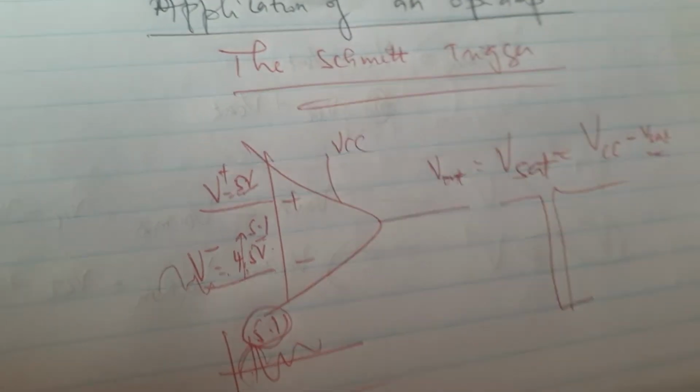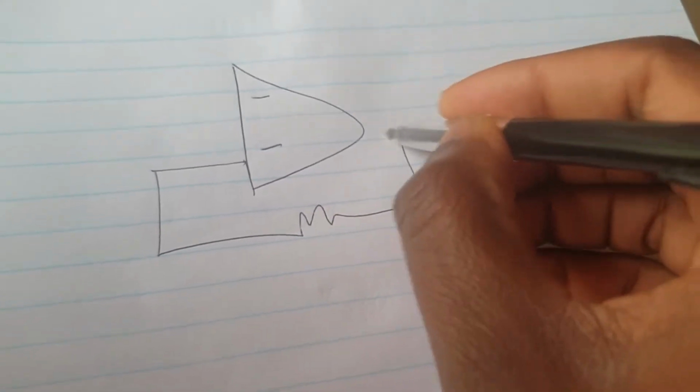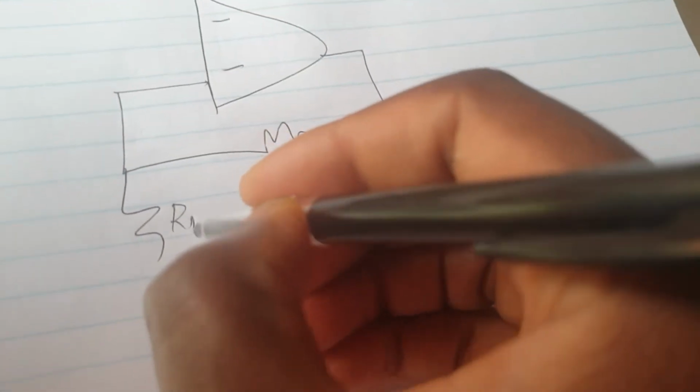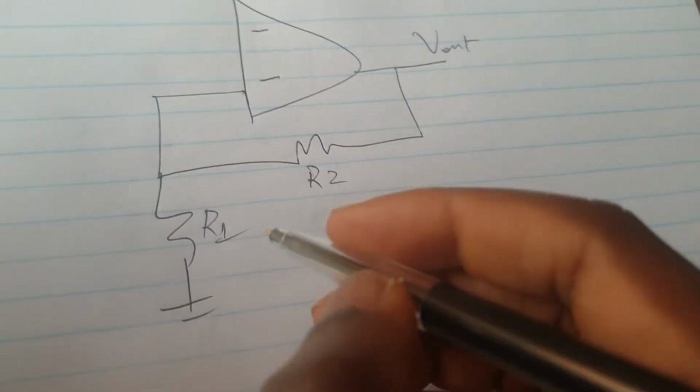And how do we design therefore a Schmitt trigger? And then we're going to learn how it ends up eliminating the impact of an unwanted or noise signal. So to design a Schmitt trigger, we still have on the reference signal side, we'll normally tie it up to a reference value with R1 and R2, which is dependent on the output, meaning by having some feedback configured with it.